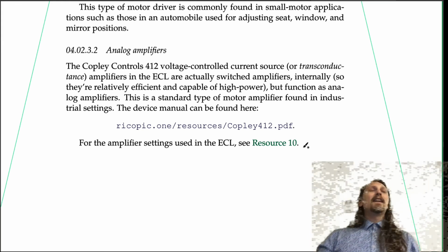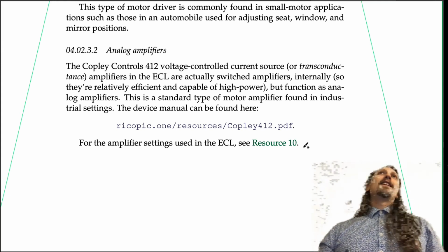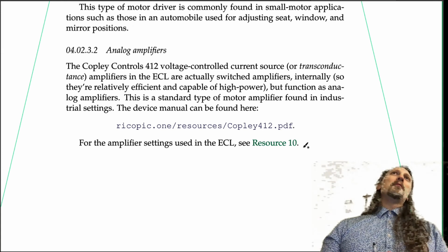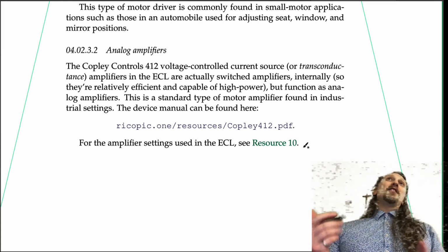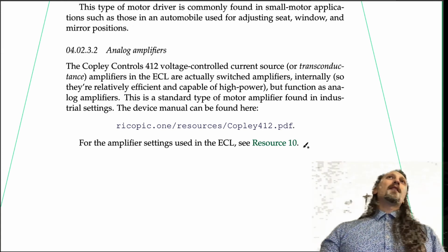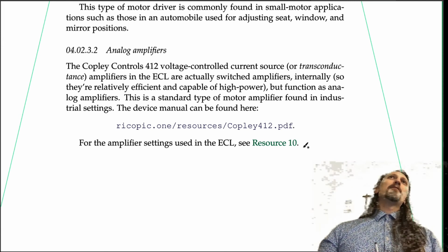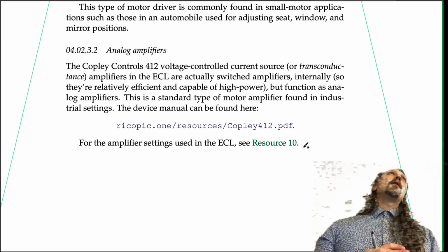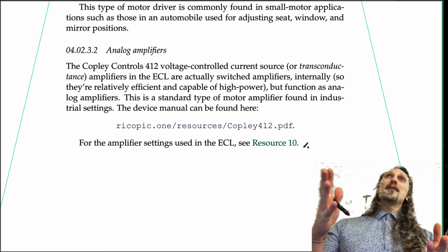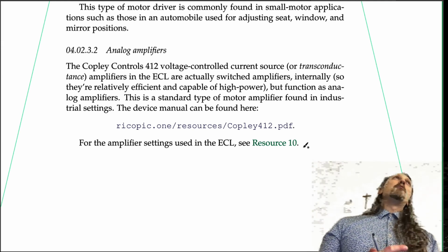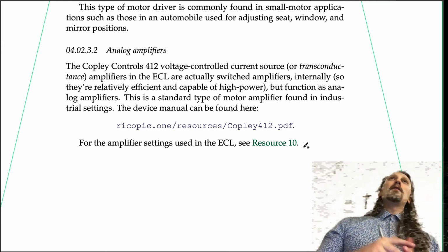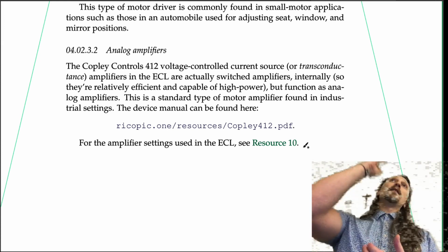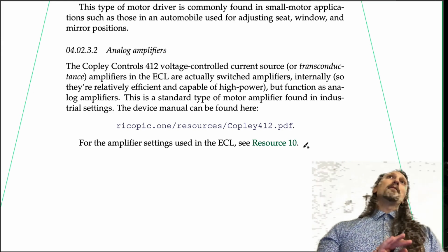And then if you run into a situation where there's too much torque, it can't turn, then you're just sending pulses and it's just heating up. But that's an issue with all motors. So yeah, pulse width modulation, although it looks kind of similar to what you do with steppers, really you want there to be the full power necessary at each pulse that you send to the stepper so that you do get the motion. Yeah.